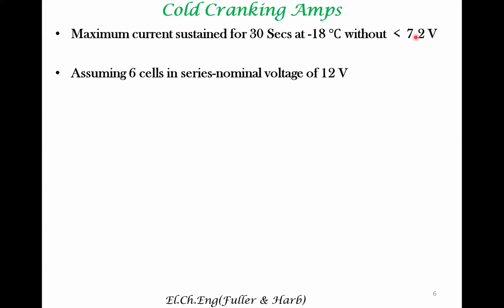Because it is cold, the voltage that can be obtained from a string of cells cannot be less than 7.2. So what is the maximum current that can be sustained for 30 seconds at minus 18 degrees centigrade without the voltage getting below 7.2? That is called cold cranking amps.